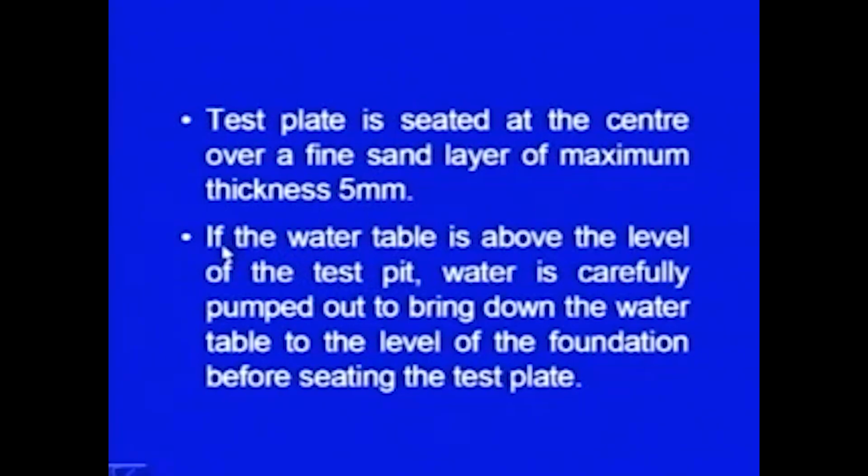Now, this is an important point, that if the water table is above the level of the test pit, then water is carefully pumped out to bring down the water table to the level of foundation before seating the test plate. So, if the water table is above, this arrangement has to be made and water has to be pumped out.